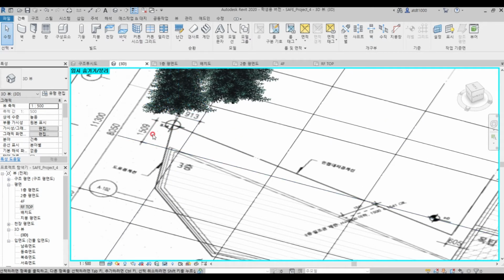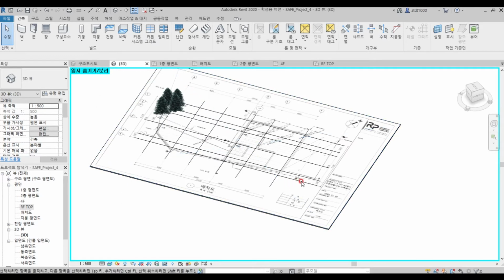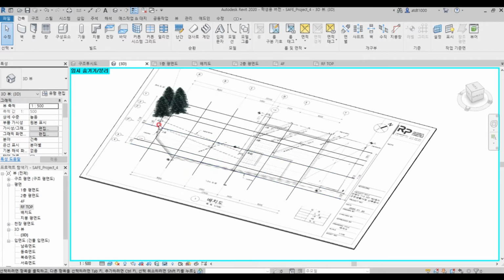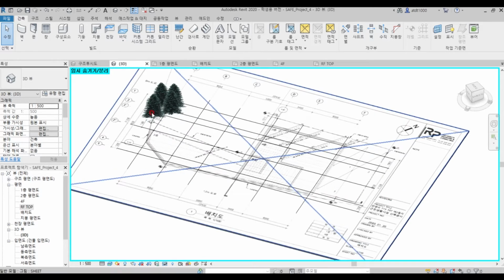Originally, there is only 1 BM point, but if the boundary of the site is abnormal or the proper reference point is absent, 2 benchmarks should be placed. So the position of the BM point should be shown in the plan. The BM point is also placed bordering a road line and having similarity with the corner of the boundary of the site.